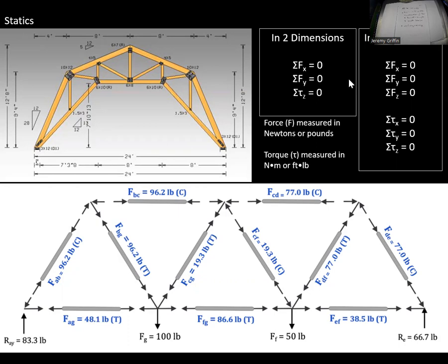That might give you some insight how you want to build that bridge. But here's the physics principles, going back to many months ago in this class. So a two-dimensional shape, like this 2D cutaway, we say, well, in the X direction or the Y direction, all the forces have to sum to zero. And on the XY plane, the torque has to sum to zero. You might call that about the Z axis if you use the right hand rule. If you have a three-dimensional structure, then it's a little fancier looking, but we've got the sum of the forces in each direction has to be zero, and also the sum of the torque about each axis also has to go to zero.